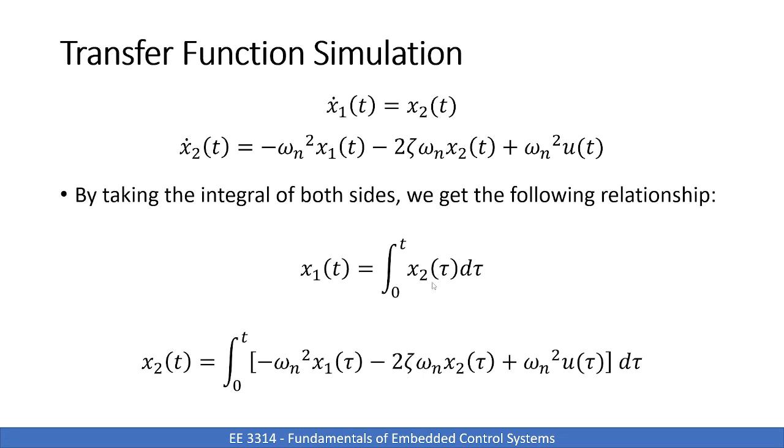So we're really just integrating our x2 variable from 0 to the current time. So we're summing up all the previous values of x2 that we've had. So very easy, nice estimation, where if x2 is misbehaved, has some really fast transitions, or even non-linearities, this integral really smooths that out and makes this x1 state variable nice and predictable, right?